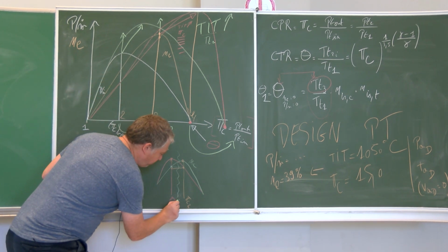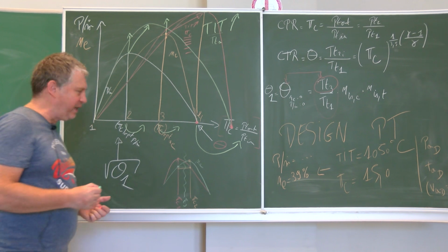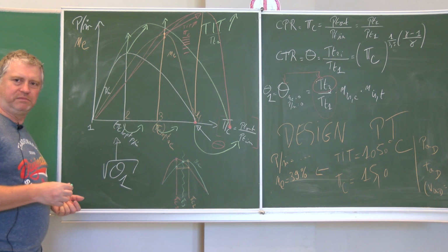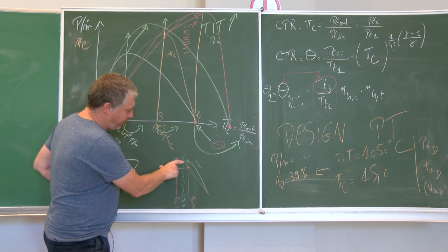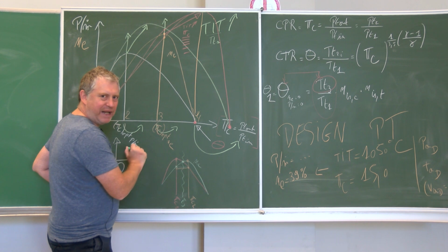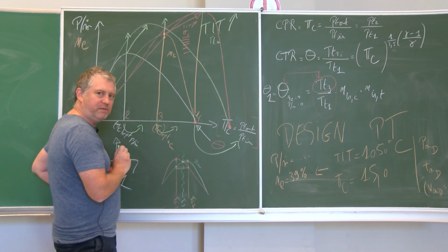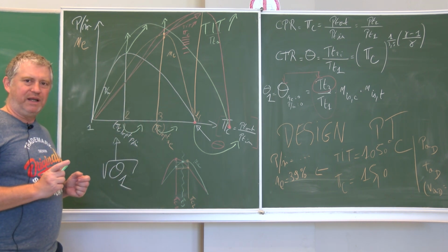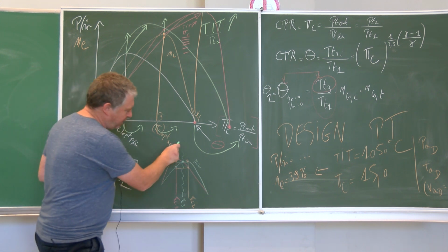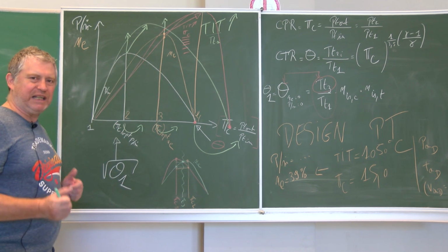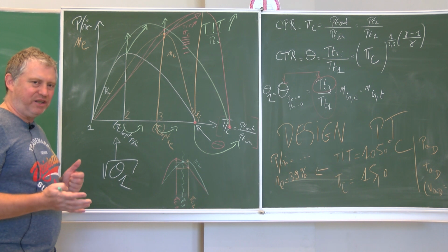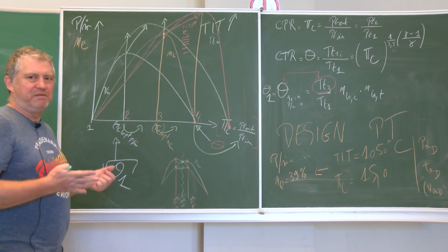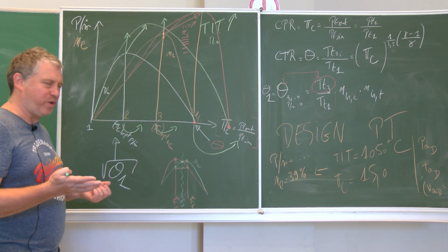Because if you choose a point that is there, a PC3, you see that you are, for example, in this point. And in this point, of course, you are burning more fuel than there, but not so much more. And of course, you are heavier than here, but not so much more. And so maybe the trade-off should be there in between. That will not give you the lightest engine, not the lowest amount of fuel burn, but the best trade-off, the best compromise in the choice. Okay?